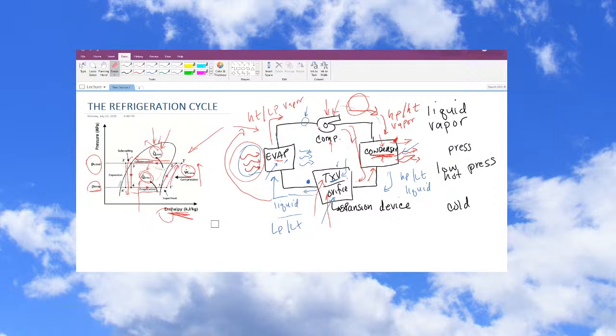So if I had a camshaft over advanced in a Subaru, for example, because of the AVCS, I short the AVCS solenoid out. I give it a full 100% signal for a second. Bam, and I watch and see if the reading responds as it should, and that tells me the oil system is functioning correctly. I short the AVCS solenoid full open, bam, the cam went full advanced. Well, it's cool. It tells me the oil system works. It tells me the gear's functioning properly. So now, is the solenoid just not functioning properly? Well, it might not be. Even though it responded to a full open signal, it could be partially clogged, and the in-between positions are not getting good oil flow or whatever.